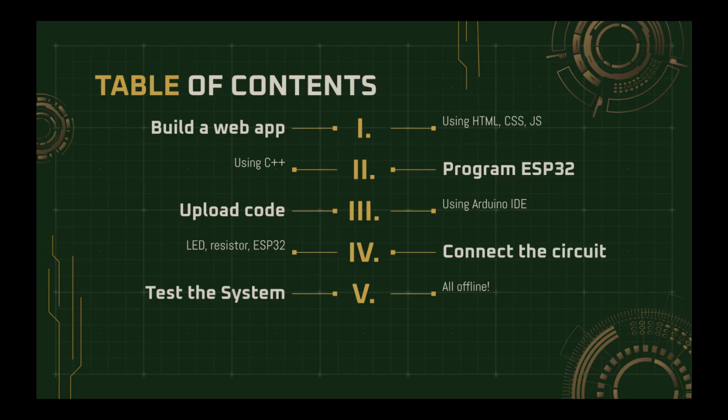Our circuit is a simple LED and a 220 ohms resistor, just to protect our ESP32 board. Of course, we're gonna need the ESP32. At the end, we're gonna test this completely offline.